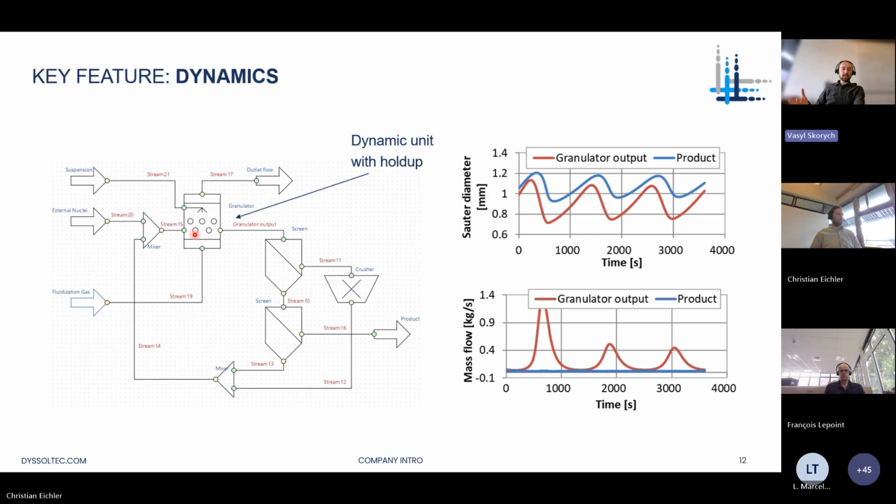We spray in a suspension, which usually contains water and a solid part. The suspension covers the particles inside the device. Then we have fluidization gas from below the unit, which makes the particles move inside and mix.